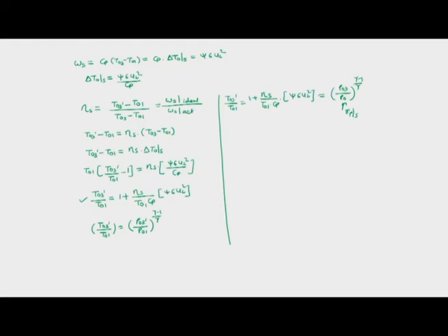So having known the velocity triangle, what else can we do? First, we can find the work required for the given compression from the velocity triangle. From the known velocities we can find the work input to the compressor. Then we can find the temperature rise in the stage, and then the pressure rise in the stage.